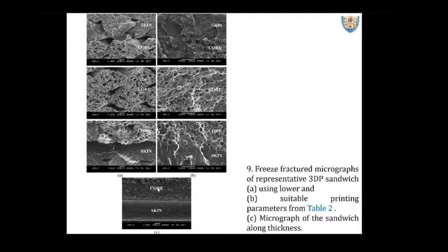Now, when you break them, what you see is in A and B. A is again the failed samples, wherein we were trying different combinations, and thereby you can see a skin here and core. Absolutely, there is no bonding at these pockets. These are known as residual microporosities. And sometimes people say that this is a non-raster. The single line is known as a raster for that matter when we print. So when they don't fuse well, this is what the pockets you see. And these porosities are bound to happen. You can minimize them. So this is what A says: for one of the parameters, how the parameters were chosen differently, and thereby how the samples went bad.